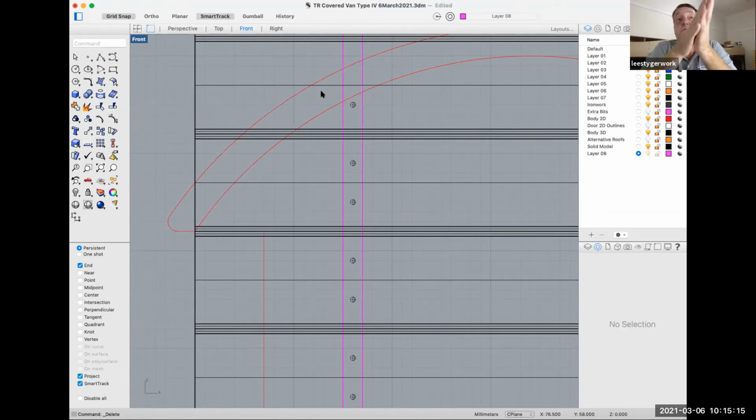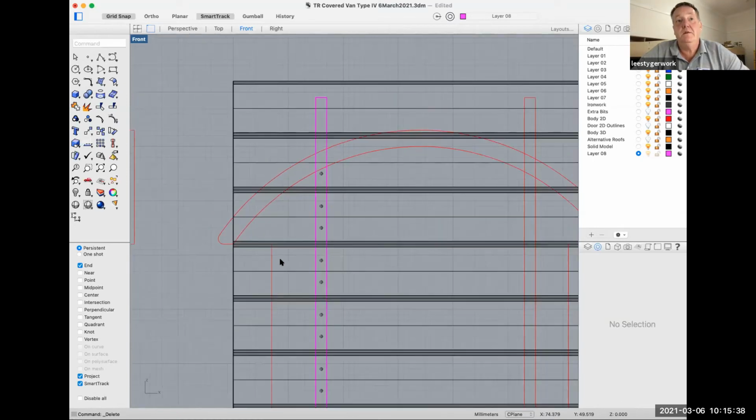The thing I found particularly daunting to begin with is, for the life of me, I couldn't work out how to do tumble homes from extruded planar solids, because obviously they need to go down one way and bend the other way. But that technique is basically by removing a curve from the other side now, and not dissimilar to the way the roof will come together.